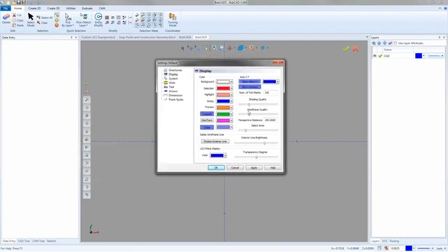Right down here's the shading and wireframe quality. This is basically the quality that you see your parts in. So some of you guys that got some of your 3-axis parts, as you zoom around and look into them, you might see some edges that, if it's supposed to be round, might look like it's made up of a bunch of straight lines. It's kind of annoying, kind of weird. It really isn't a problem, but a lot of times it can be confusing when you're going to try and pick an edge and it's a round edge and it looks squared off. It's usually the graphics quality.